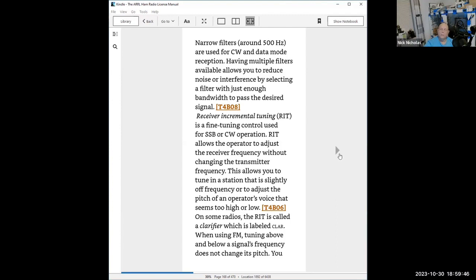So if your high pass filter is set at 100 kilohertz, everything above 100 kilohertz will go through to the receiver. Everything below 100 kilohertz will not go anywhere but to ground. There are also low pass filters. Low pass filters will allow anything below a frequency to go through, but nothing above it. A low pass filter tuned to 100 kilohertz gets rid of everything above 100 kilohertz, which will go to ground.